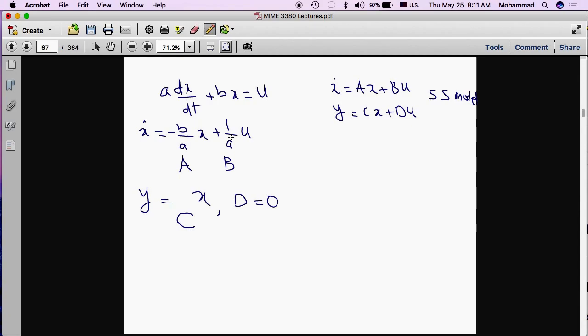So it's algebra basically. You have your equation, you rewrite it through algebra and find the first portion of the state space model. And there is only one choice here. Our output can't be anything other than x, which is the only state variable we have. So we simply write y is equal to x, and there is nothing after that. So it's plus 0 times u.